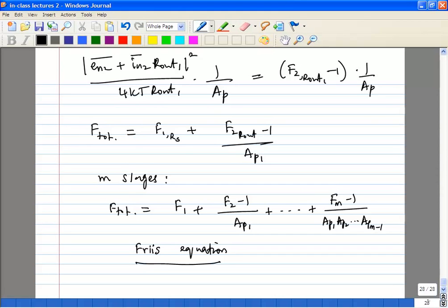Okay, so in the homework problem, I'll make you decide the noise figure and IIP3 of a certain system. We'll take a cascade, like maybe a direct conversion receiver with 3 or 4 blocks, and for some blocks I'll give you some of the parameters, IIP3 or noise figure, and you'll be asked to calculate. You can put it into an Excel file if you want, you can use MATLAB, whatever you want. You can try to trade off and come up with reasonable values for all of these. Okay?